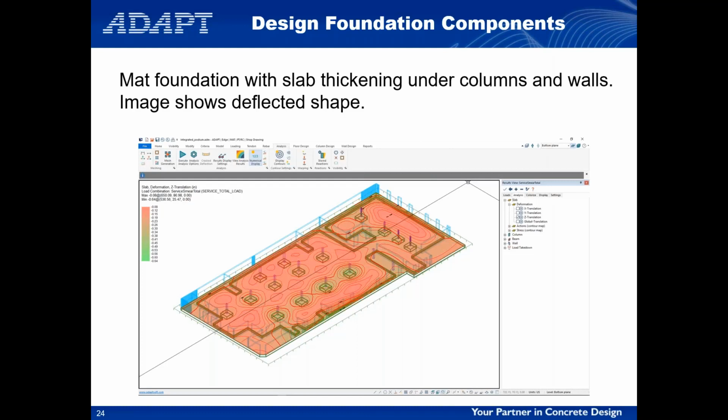Then you would go and complete the design of the foundation in no different way than you would with Floor Pro for the Podium. We're laying out our support lines. We're checking with the difference here. You would also check your maximum soil pressures and other things, but the design process is exactly the same.